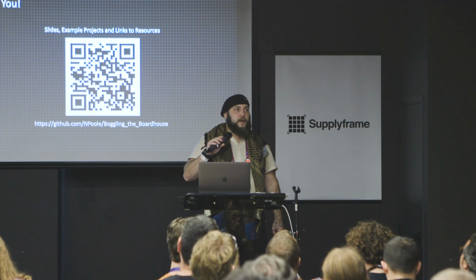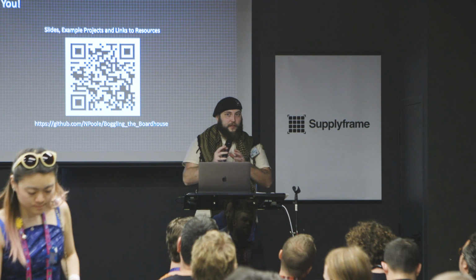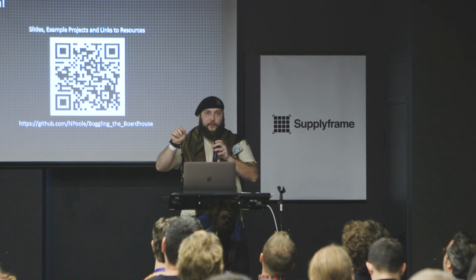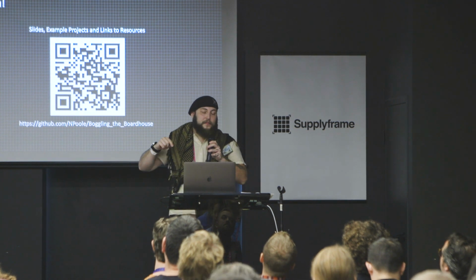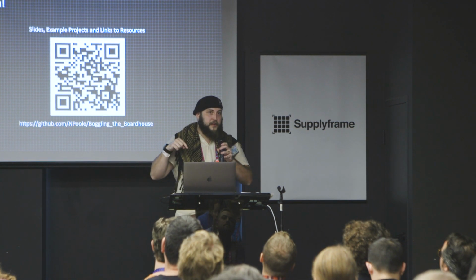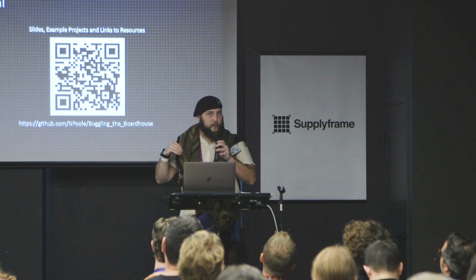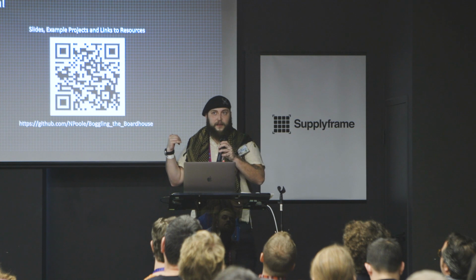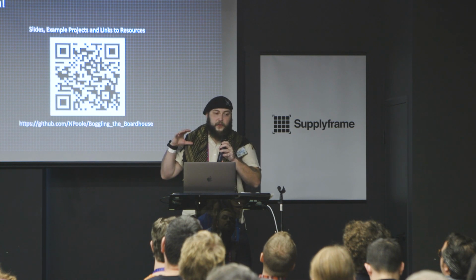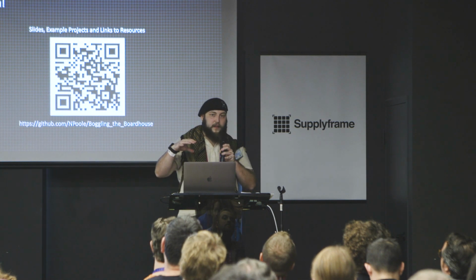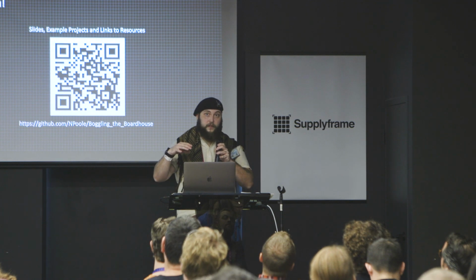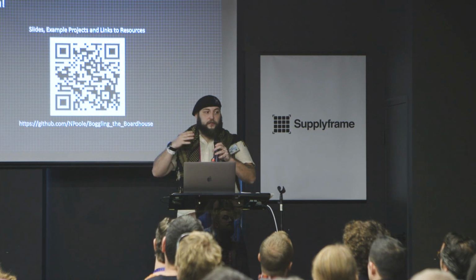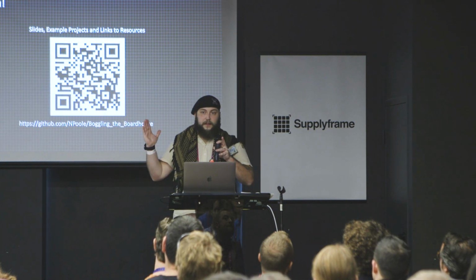The question was how do you handle a keep out for the copper on the edge of the board when you're doing those Bendy Tab buttons? Board houses generally don't care how close to the edge you get with the copper pour. What you end up doing a lot is finding a balance between explicitly telling your design tool that this is a keep out, using something like the keep out layer in Eagle, and also adjusting your general design rules to make your